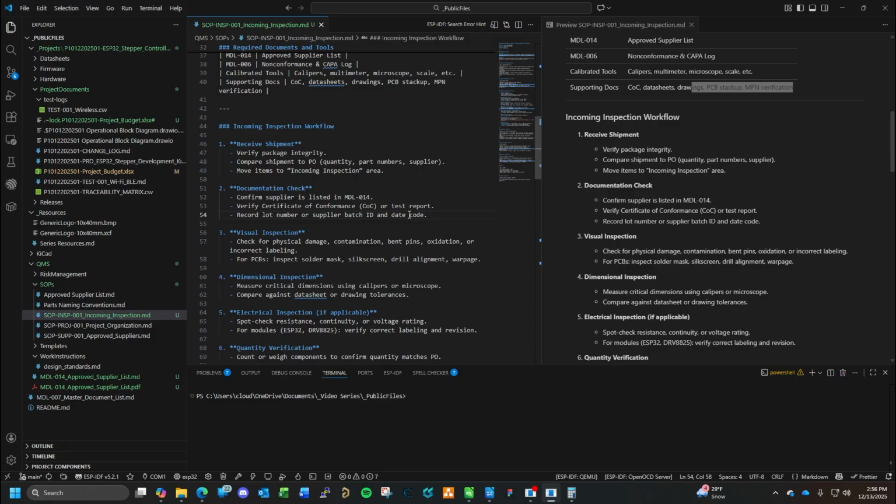So we definitely want the date code, because with a lot of electronic parts, you want to make sure you go FIFO, first in, first out, or use up the oldest stock. Even though, let's say you order the same part two weeks apart, the part that you receive later could actually have an older manufacturing date code. Could be old stock that they found, or if you ordered it from a different vendor, could be older stock. You want to try to use up older date codes first.